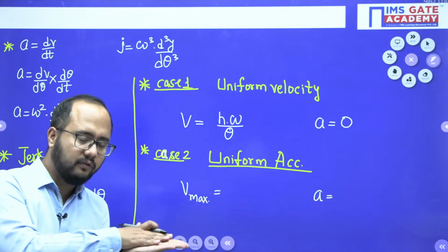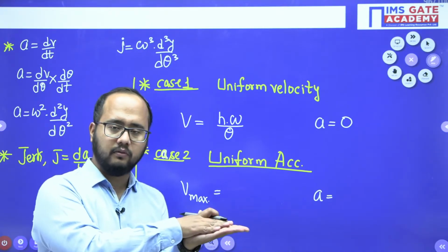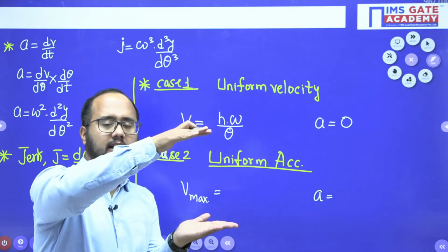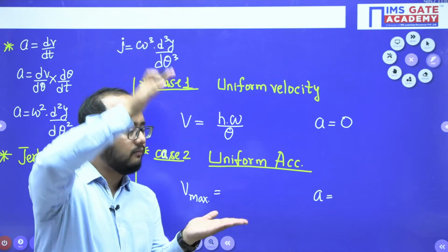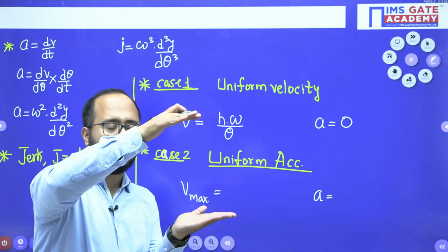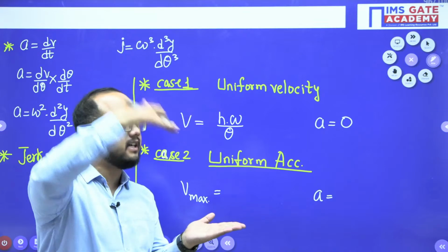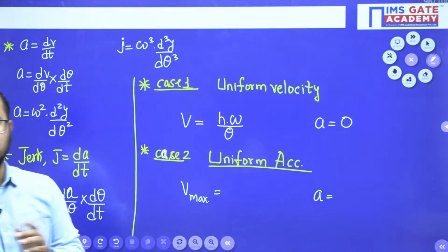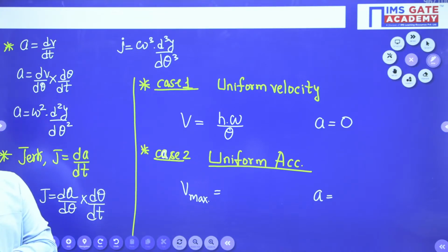See, it starts from the motion here. Let's suppose this is the starting point of the follower motion. It starts, and at the mid, okay, it will change. So from starting to the midpoint, it will accelerate, positive acceleration, and after that it will negatively accelerate. So at the mid only it will have the maximum velocity actually, not the acceleration. Acceleration is constant here.